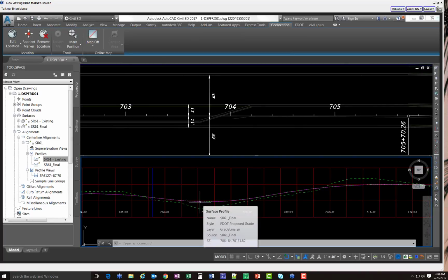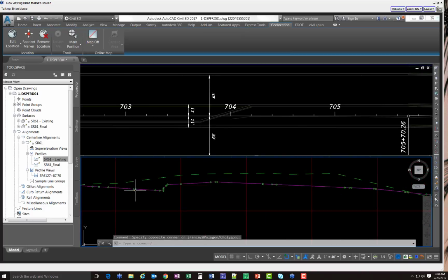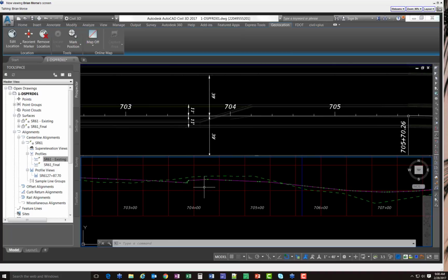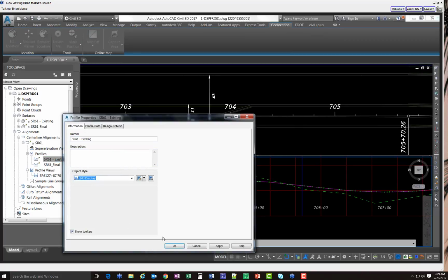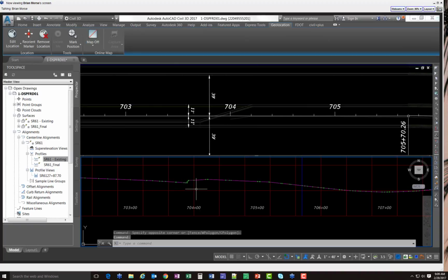So what happens at the offsets? Well, if this is a crowned road, then we should see the traveled way or lane lines on the inside here. They should be just below the center line elevations, considering, you know, crowned road situation. And of course, you'll see some weird things going on where the alignment will hit the median and then jump up a little bit. So that happens like right here. So we're not going to follow that. That would be kind of rough to drive on. So we're going to make something nice and smooth. Alrighty, so let's just shut this off. No display. And we'll get cracking on this thing.